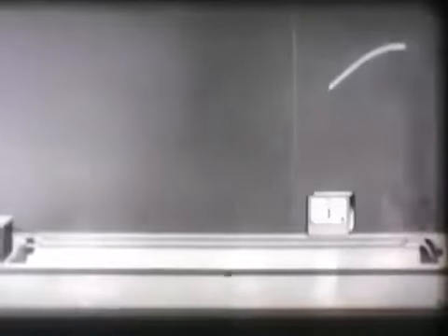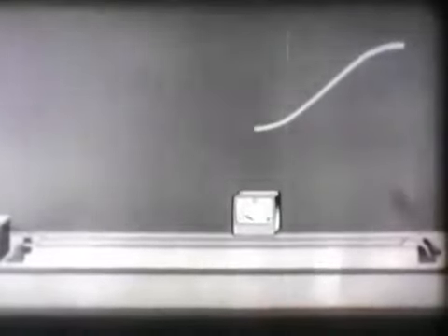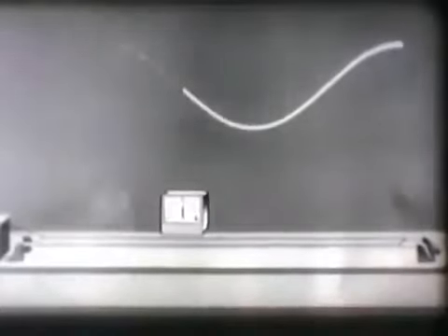The standing wave of current on the transmission line can be plotted as easily as the voltage. It is a closed circuit. At the shorted end, the current reading is maximum for the line. A half wavelength down, the current is again maximum, and so on to complete the standing wave of current.